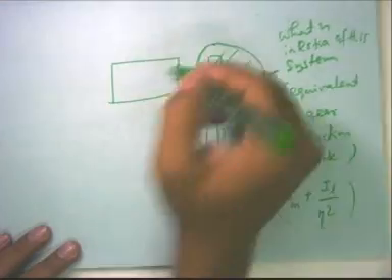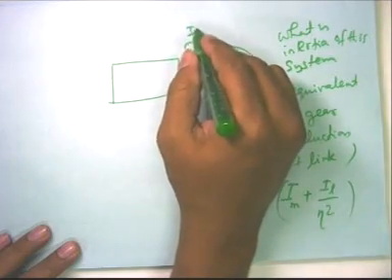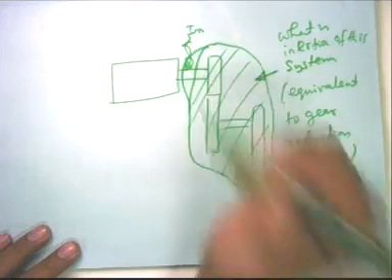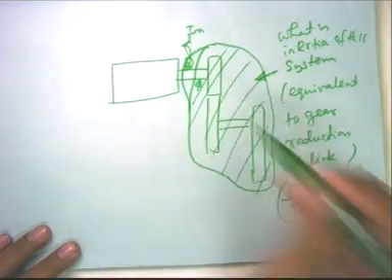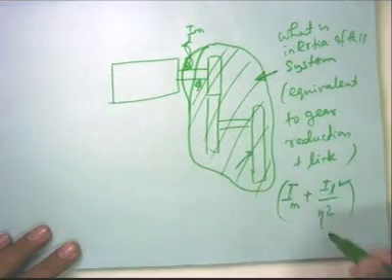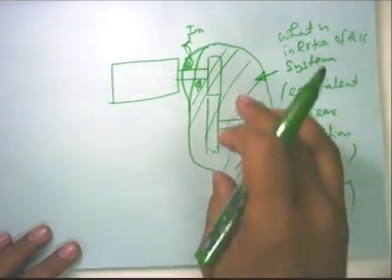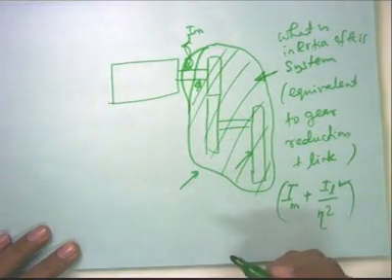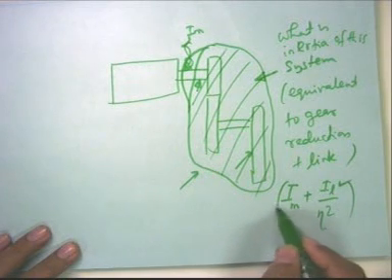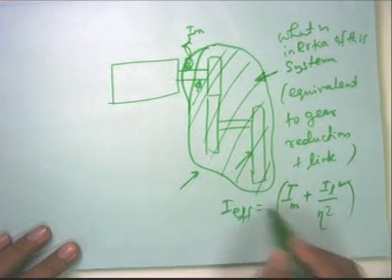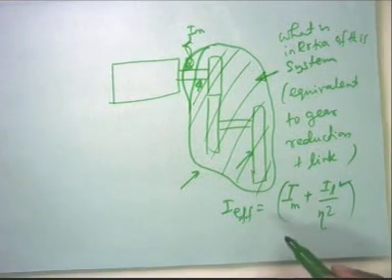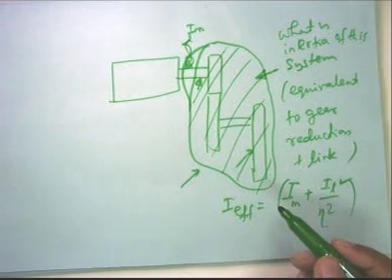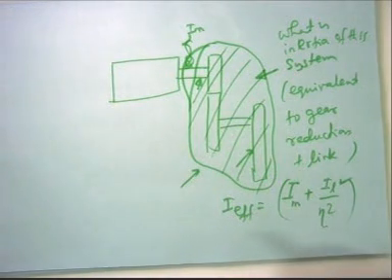I_m is this portion, I_L is this portion, and this is eta square. If you want to think of this whole arrangement as one link, then this link's inertia is this one. It is an effective inertia, meaning the gearbox has an effect on the dynamic motion. So this is called effective inertia.